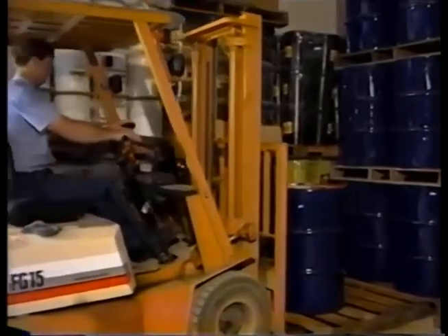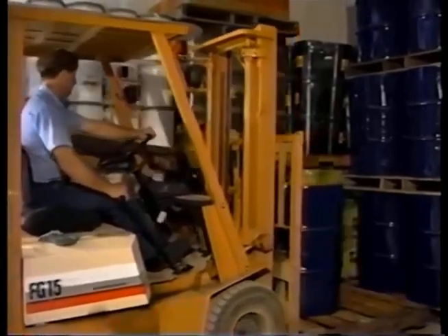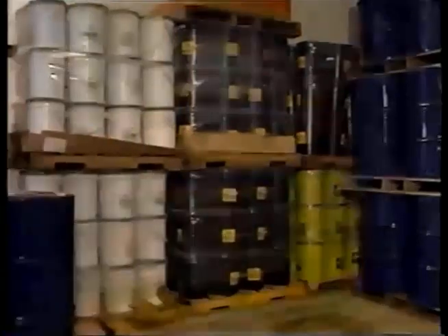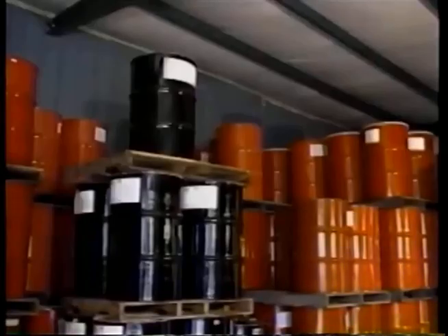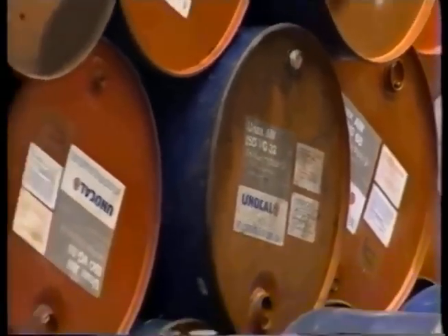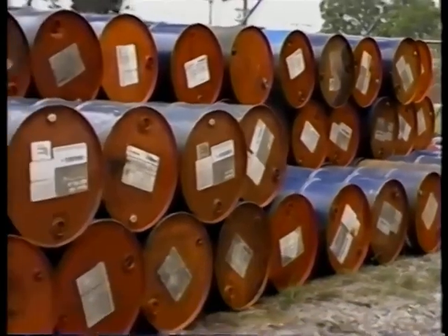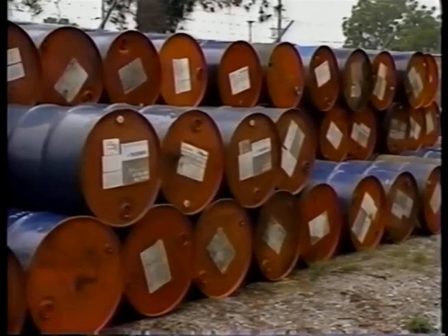Now, we've discussed the advantages and disadvantages of various types of fluids and their properties. Let's take a look at a few important guidelines you need to follow when bringing any hydraulic fluid into your plant. First of all, whenever possible, hydraulic fluid should be stored in a clean, dry place. If you have to store them outside, make sure the drums are turned on their sides so rainwater cannot collect on the top and be pulled in past the seal by changes in atmospheric pressure and in temperature.